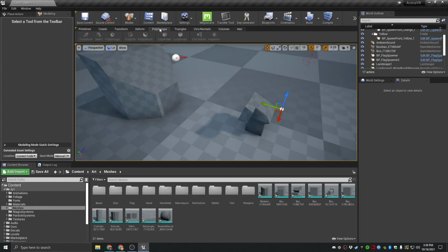What's the general gist of the shape, right? Is it roughly a spherical shape? Great, then I'll start from a sphere. Is it roughly a box shape? Do I need a little bit more of a complex profile to start from? Then I might choose a polygon. If it's a wall, I might choose a polypath. Is it cylindrical? I might choose a polyrevolve.